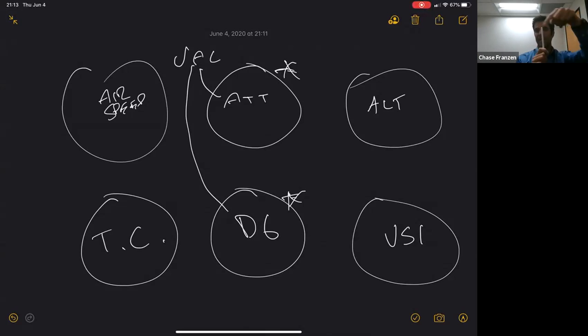Imagine I've got a spinning wheel on this pencil. If it's spinning fast, it's very difficult for me to move this pencil like this. Very difficult. And that's because of a principle called rigidity in space. So a gyro that's spinning is very resistant to me moving it.